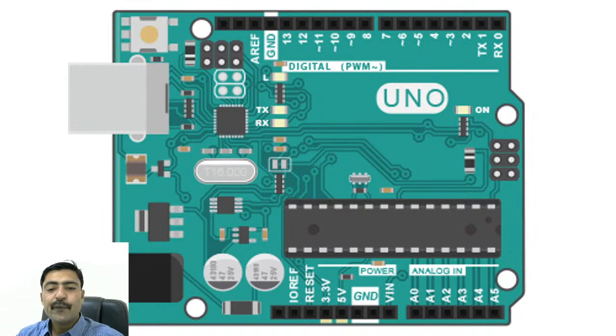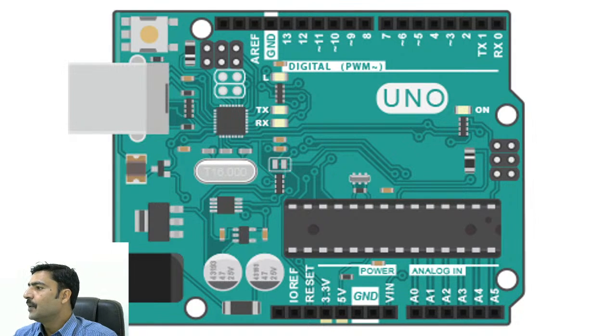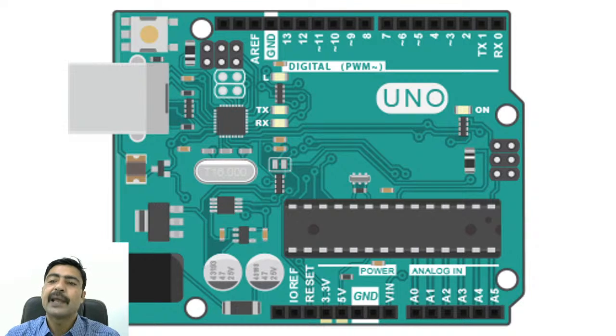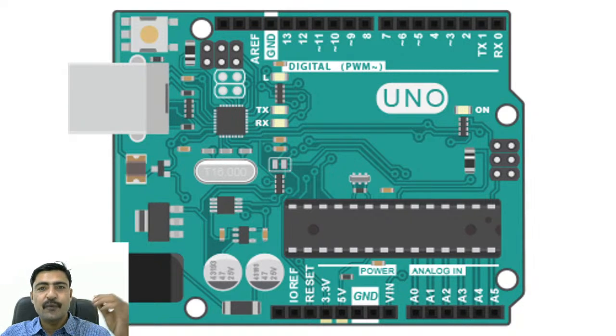To drive this Arduino board, we supply it with a battery of minimum 5 volt to 12, maximum 15 volt. But I recommend you apply 12 volt maximum. Internally, microcontrollers or your Arduino board use a 5 volt DC power supply. Don't get confused, don't think these things are going over your head, because this is totally new. Just keep one thing in your mind: we feed it by an external battery, from 5 volt up to 12 volt, and we can program it using a USB cable.